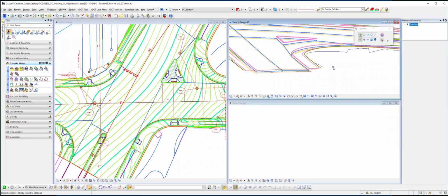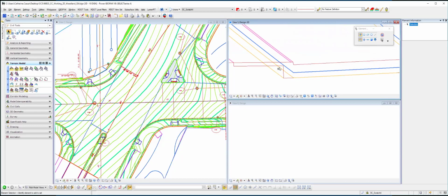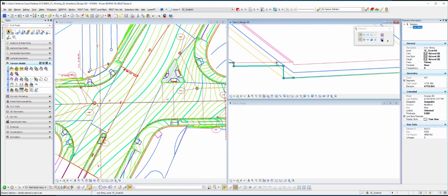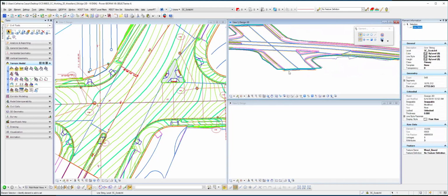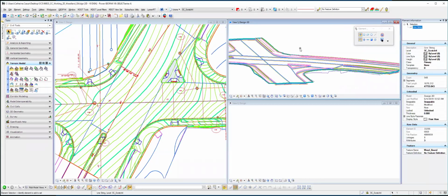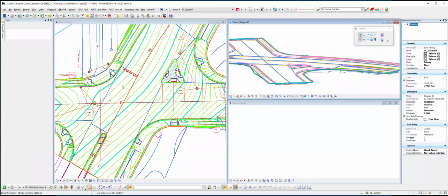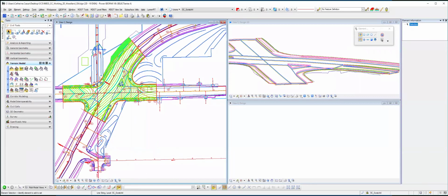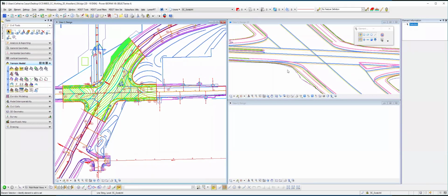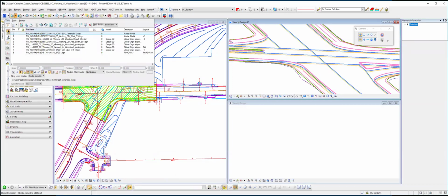All right, so here are the two different boundaries. I made a boundary because we had a subgrade surface here and a top surface. So these boundaries were created because I had a bunch of different things that I was also connecting to. You'll see here I've got different surface models. These are from different models as well as another one on this side. So these boundary elements were used to make sure that I was interconnecting with all of those different models.